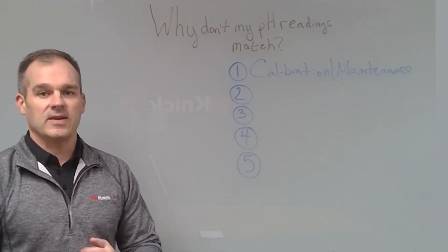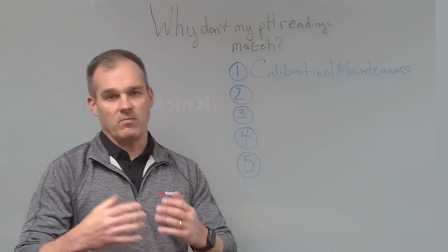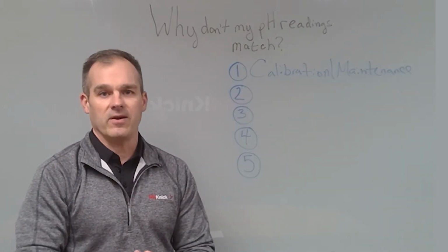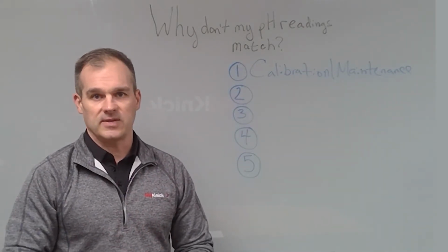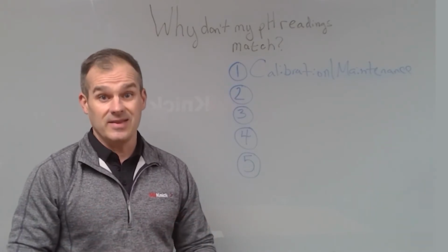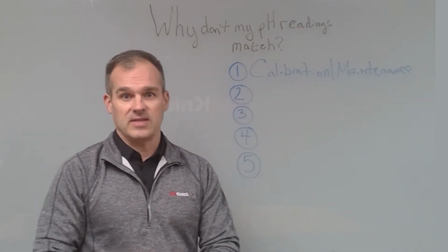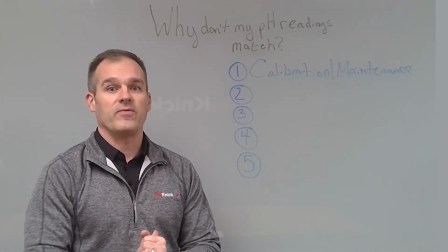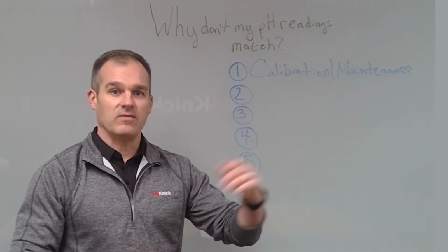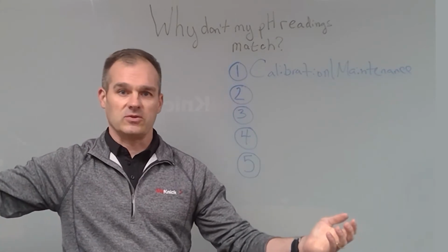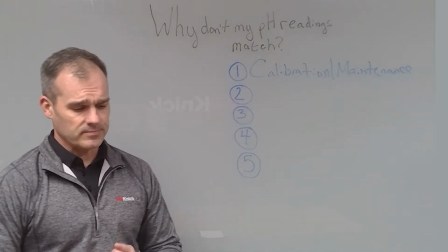With regard to frequency, it really depends on the application and more so on what type of wear or buildup are you getting on the sensor. If the sensor is not cleaned frequently, if you're seeing fouling, things of that nature, that could affect the accuracy of your inline measurement versus your reference measurement.